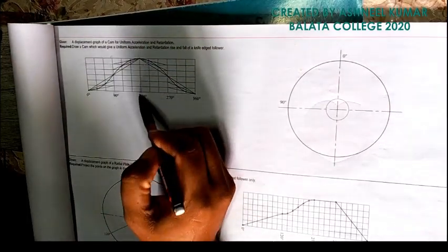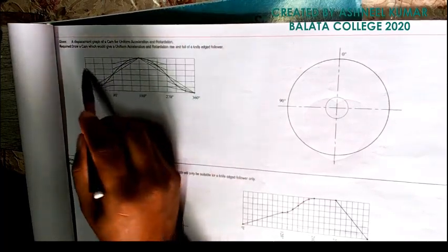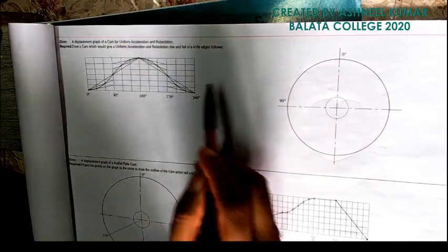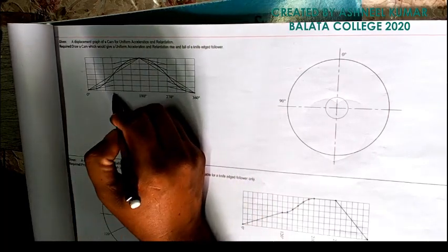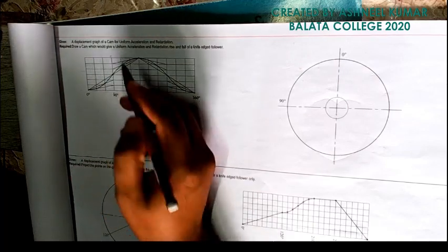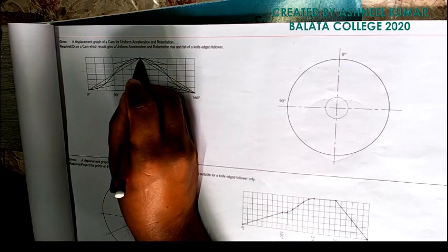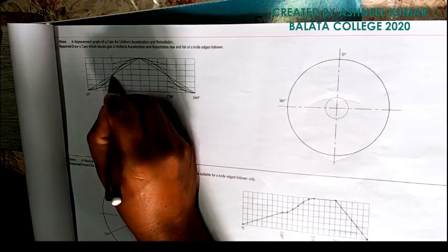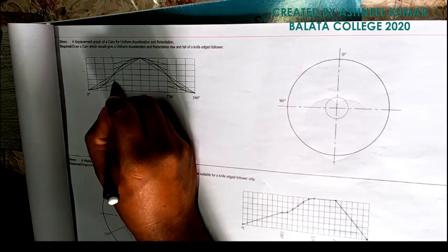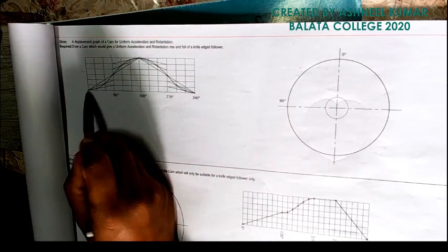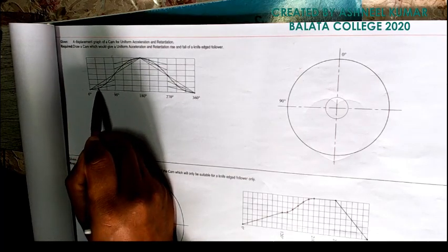Why 6? Because from 0 to 180 we have 6 lines here, so we need 6 horizontal lines also, and these horizontal lines can be used to draw the curve that side. Now the middle one is 90, half of 180. You just draw one diagonal from 0 to the top where 180 is. That's your midpoint. Now the points lying below, this one and this one, you join to the 0. So the first line, that's your point.